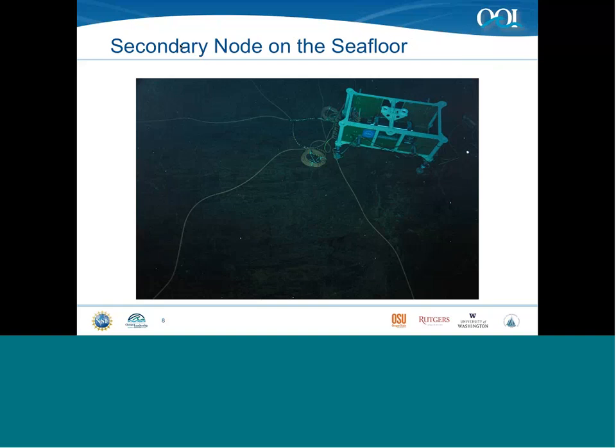The one thing I'll point to is in the middle, on the top of the junction box, there's 2 latches. Those are called Perry-Slingsby latches, and that's what allows the ROV to latch into the junction box. It can support several thousand pounds. That kind of latching can be used for instrument packages as well. We can provide details on how to construct a latch that's compatible with that system.